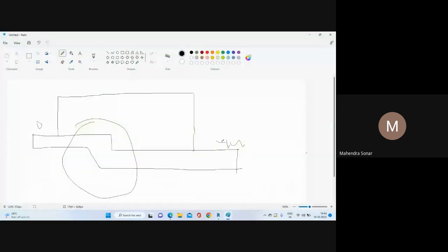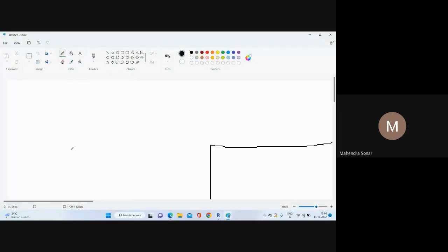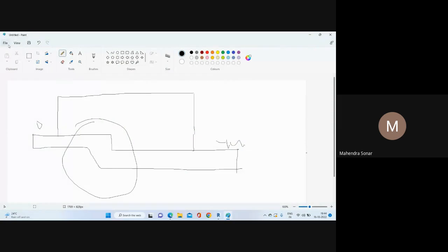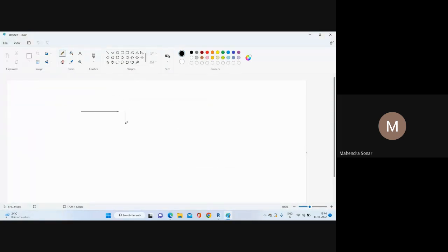So if I show the reinforcement section here, I will just click new. Just consider this is a step footing like that. In that case our slab reinforcement comes and goes down here, and this is your bottom reinforcement, and this is your transverse direction reinforcement like that.